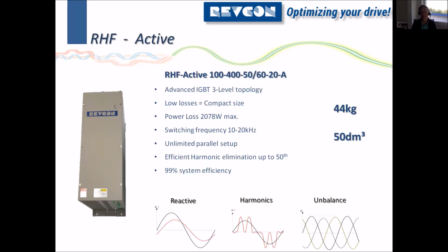Some brands already have this topology on the market. Some are still keeping on with the 2-level design, which makes the whole solution bigger and more expensive. But nevertheless, I think this is not unique to our technology. We have a good setup. We have put some effort into the lifetime expectancy of the product. So for example, for a 100 amp unit, we use a 300 amp IGBT module inside, which is one of the reasons why the design is very good in the long term and will be a long-lasting design.